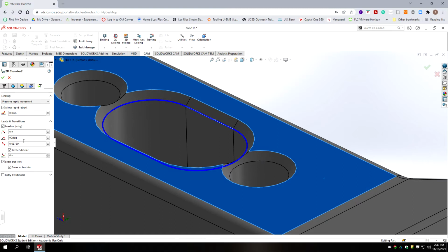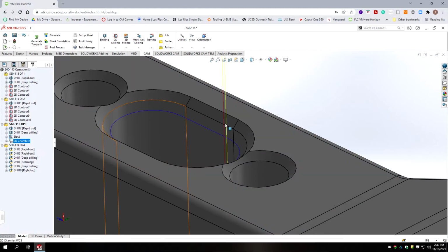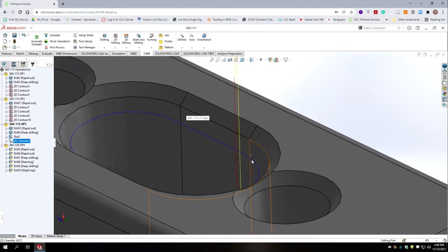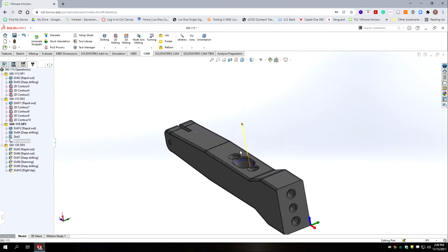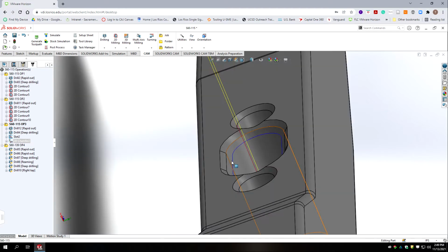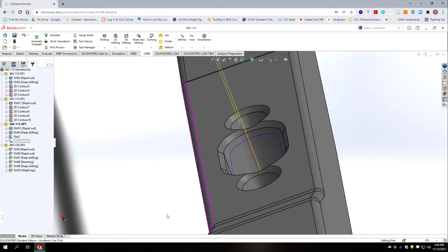We're not going to do any radiuses. We're coming at 90 degrees. Our lead in is going to be significantly smaller now. Let's go 0.01. We'll leave perpendicular on if that may or may not help. 0 on a lead in vertical radius, and we're going to lead out at the same. So accept. And we get a tool path, and what this represents is actually the tip of the tool is going to be sitting lower, very tip of the tool, and then the side of the chamfer mill will cut our chamfer.